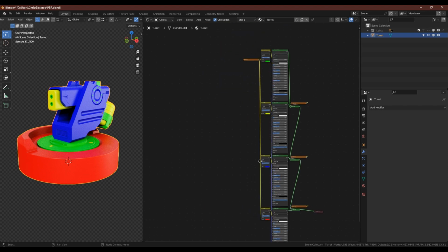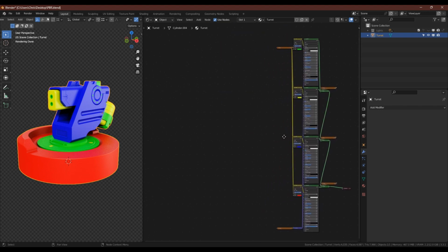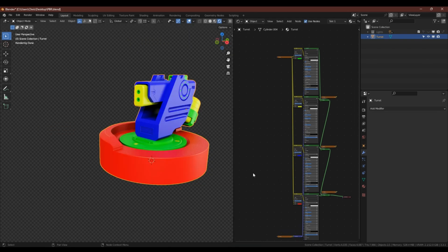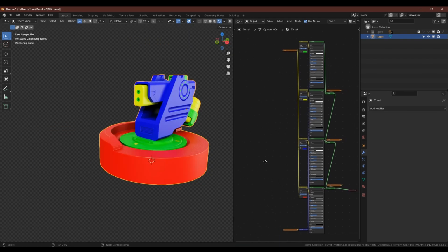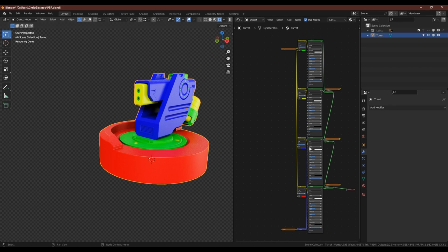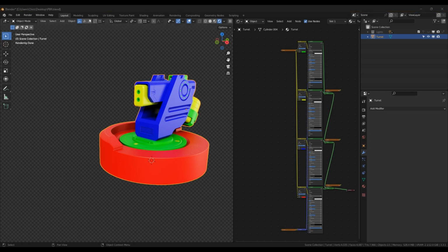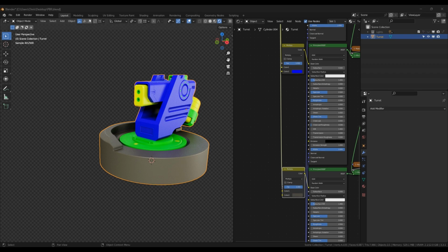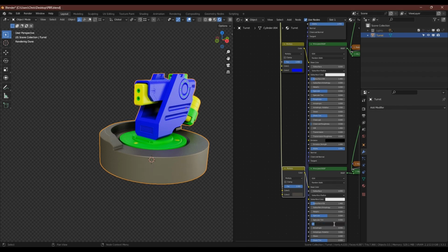Once those are all connected up, we're now ready. We can procedurally texture each individual map. Just going to save that out for now. And one last thing we can do is, if you remember the materials we set up for the high poly, I've copied the hex numbers for all of the colors into a notepad file, and we can just paste those in. And if we set the metal value and the roughness to the same, this will now look identical to the high poly that we modelled earlier when we picked out our colour scheme.